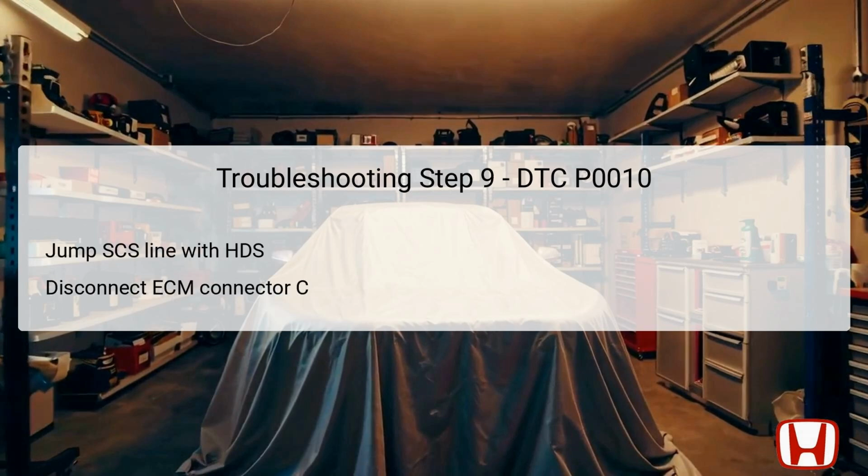The 9th troubleshooting step involves jumping the SCS line using the Honda Diagnostic System, HDS. The SCS line, or Service Check Signal Line, allows technicians to perform specific diagnostic tests and functions within the system. Jumping this line prepares the system for the next stages of troubleshooting by bypassing certain safety measures, thereby allowing technicians to check for stored codes and functionality of the system.